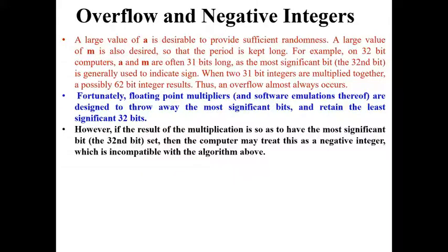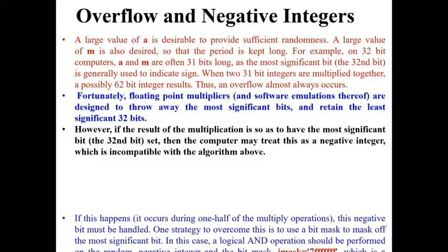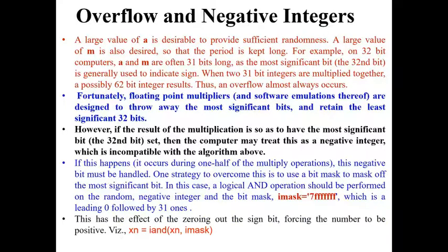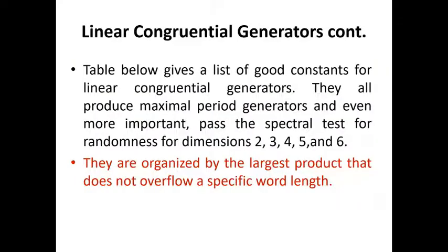And most computers will use their MSB bit as the sign bit. So if that MSB bit is 1, it will consider it as a negative number. So the most preferred alternative to work with such cases is to mask the sign bit, or mask the most significant bit. So we'll use this pattern 7 followed by all FF to mask the MSB bit. Okay. So with that,